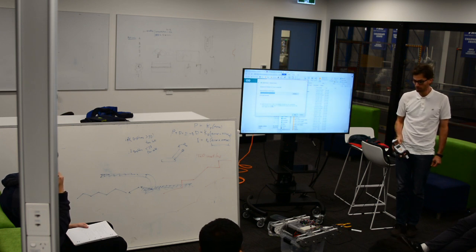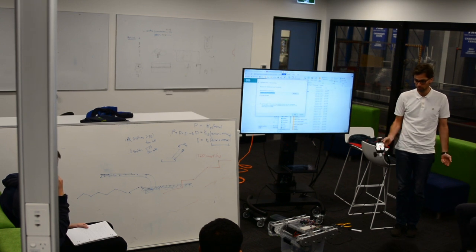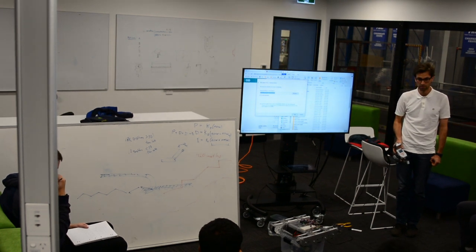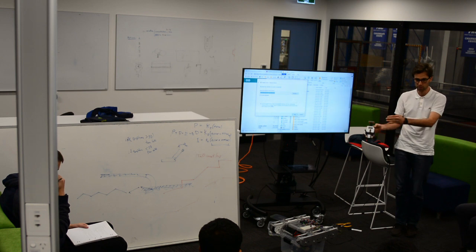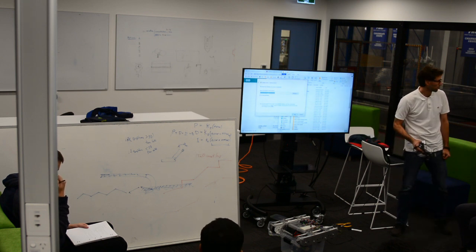Using encoders on the wheels, this seems to work pretty well. I think we could probably run that system over and over again quite a few times, and it's going to work, until eventually it starts to drift and twist, and then you lose it, right? But every time you have wheel slip, you lose it.